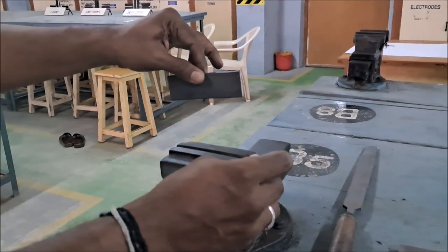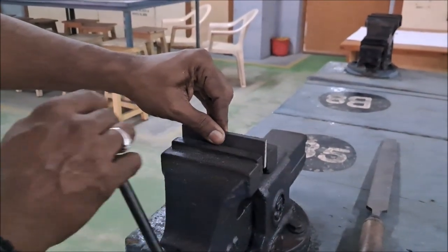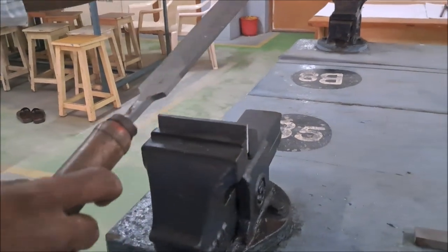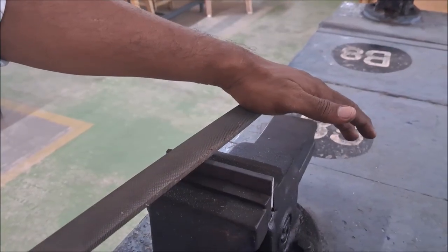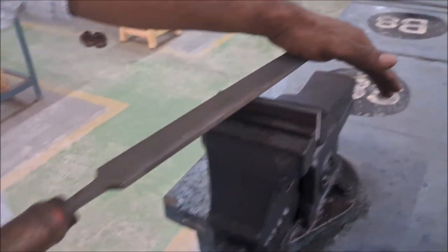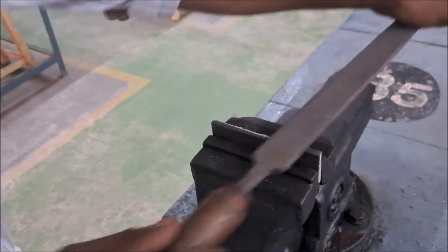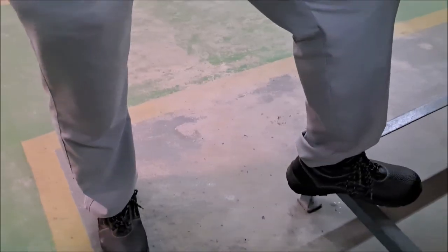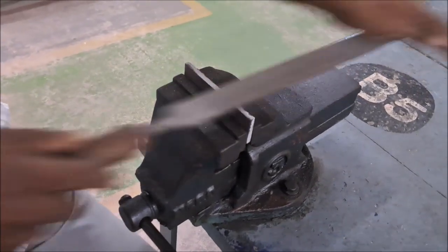Now, when you loosen this, then tighten it. Hold it tightly and rigidly. Now using the flat file to make it smooth. The left hand holds the front edge of the file, the right hand holds the handle. Now using the file to make the flat surface. When you file, use the same procedure, forward and backward direction. This is the right standing position. Then only you get the grip. You have to stand firmly, otherwise you will fall down. So when you stand like this, then you have to do the filing.